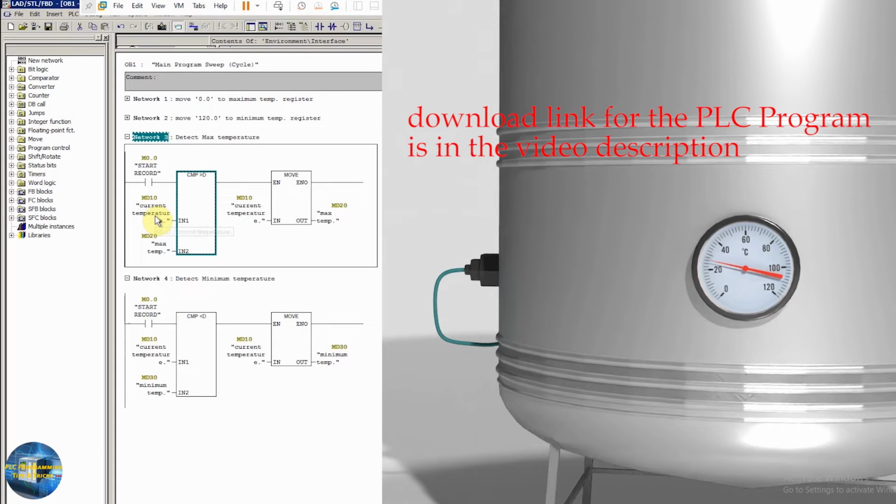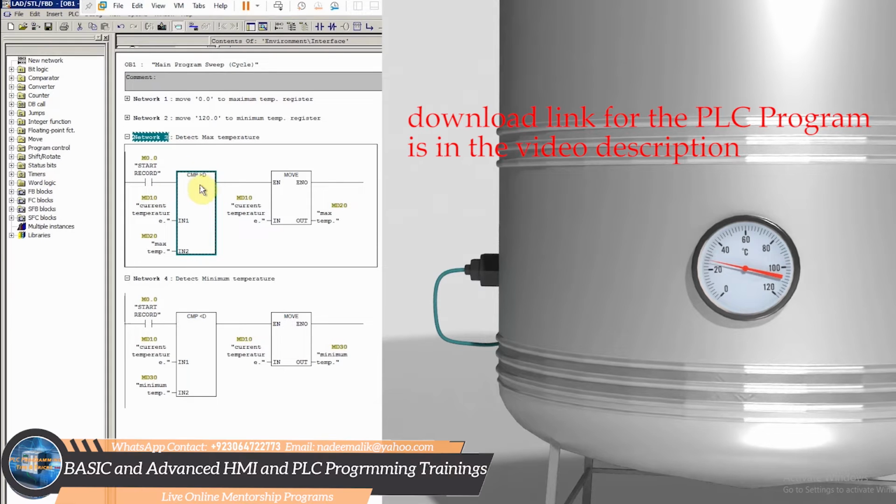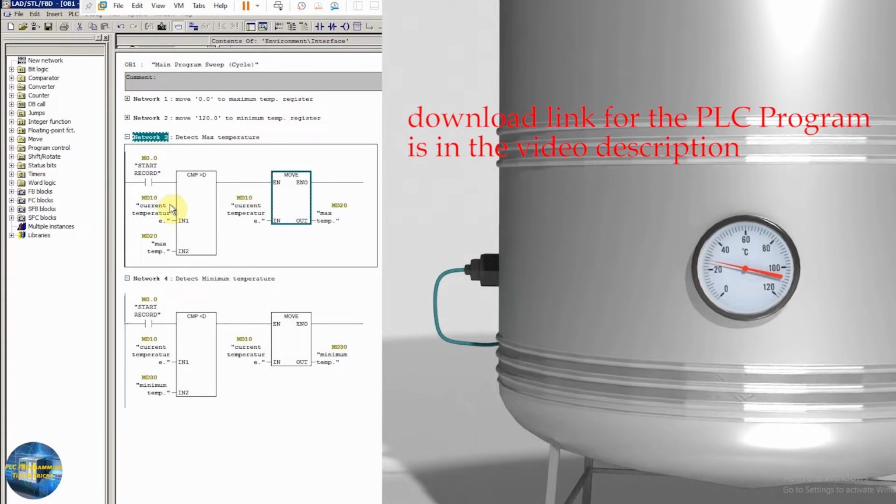For example, at that moment our temperature is 15 degrees. This 15 degrees is more than 0.0 degrees. So the comparison instruction result becomes true, and we have a move command here. It will move our current value of 15 degrees into the MD20 data register. So this value will be updated here as 15 degrees.